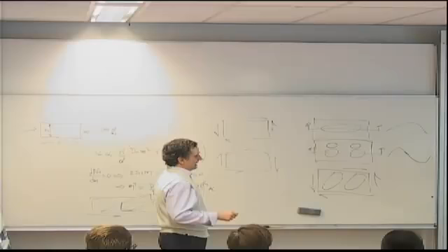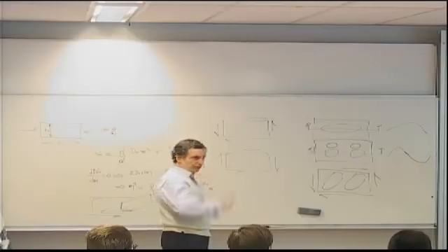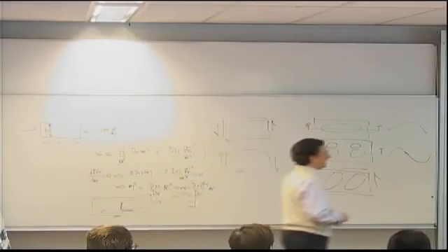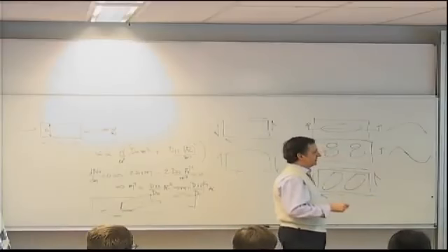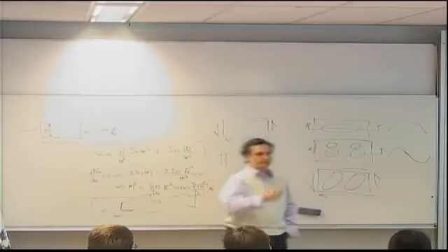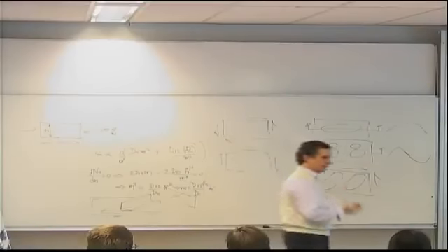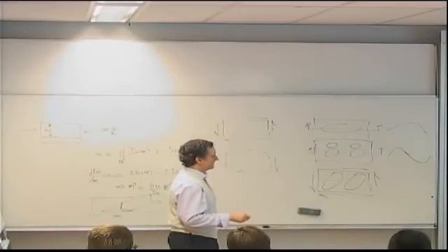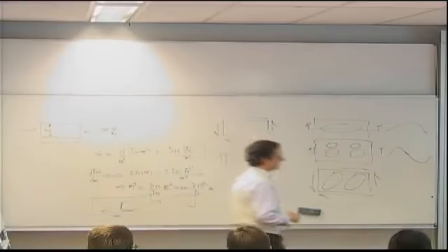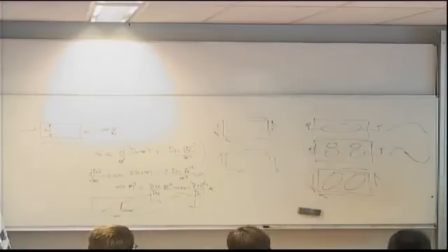So my NX and NXY, I have two applied forces that are constant. And the same way as before, we take the ratio, the shear divided by the axial load, to be K. That means our answer will be a function of that ratio. We change the ratio, we find a different solution to the problem. And D16 and D26 are going to be 0 because otherwise the algebra becomes much more complex.